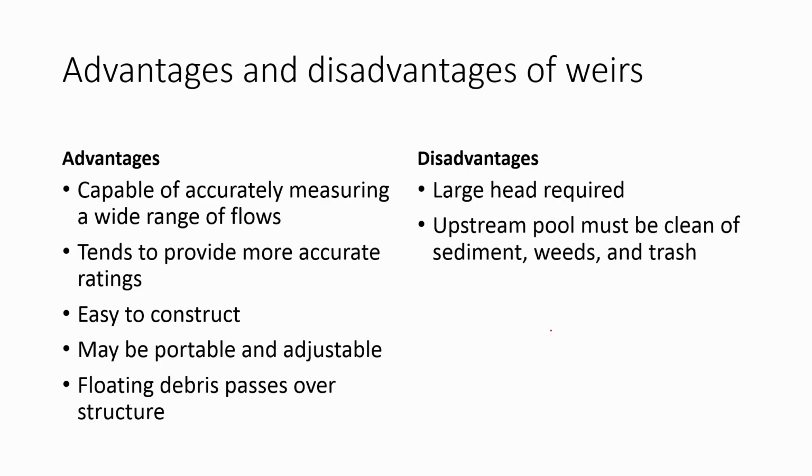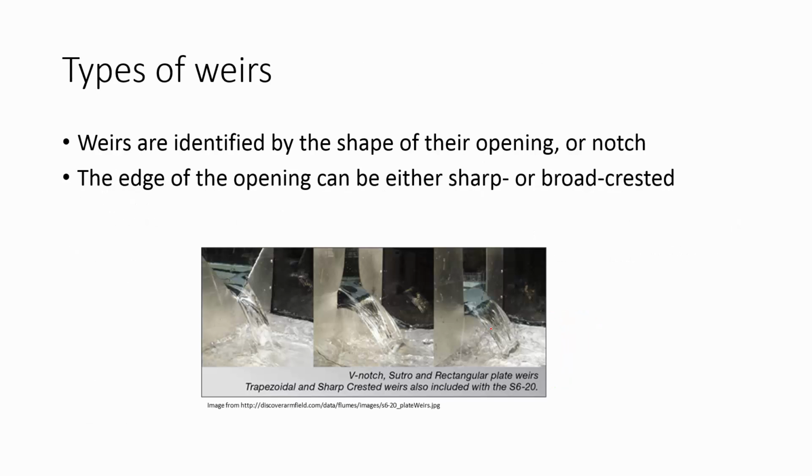So if you have your weir structure and here's water, what happens is that upstream you can have accumulation of dirt at the bottom, and that will affect your reading. So you need to keep it clean upstream from where you make the measurements.